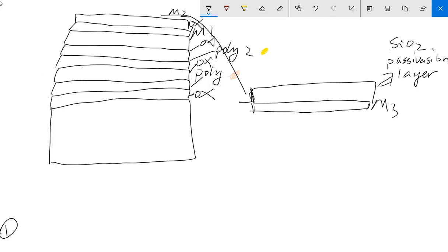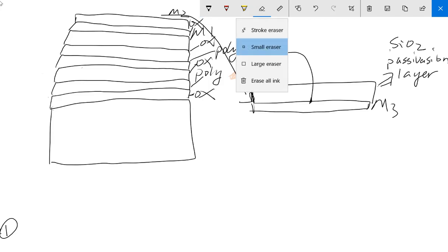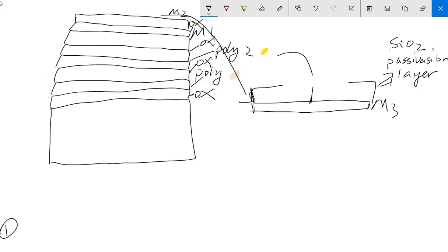If you do not have an opening, how can you connect this to the outside of the chip, right? To the pins of the chip. So actually you need an opening here, so you can connect this bonding wire to the chip. And you have so many other layers at the bottom, for example, N plus, right? And so on. So that's a P sub.